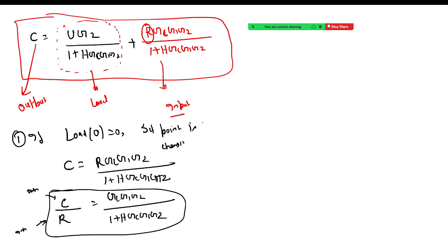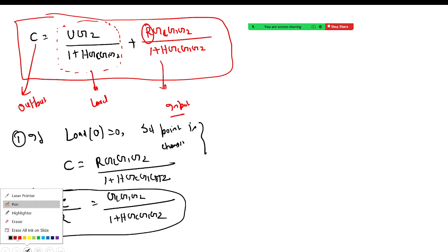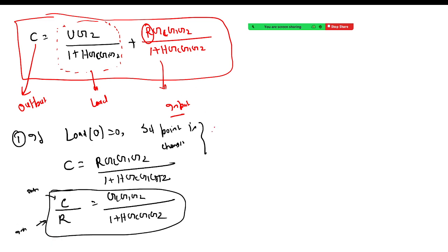And if this kind of problem is there, this problem is called the servo problem. In the servo problem, generally we assume our load U is 0 and we will be changing our set point, that is your R. R will be changing, and with that we will be getting the output by input, that is set point change. We will be observing the dynamics of the output with respect to change in the set point, right? This was the first case.